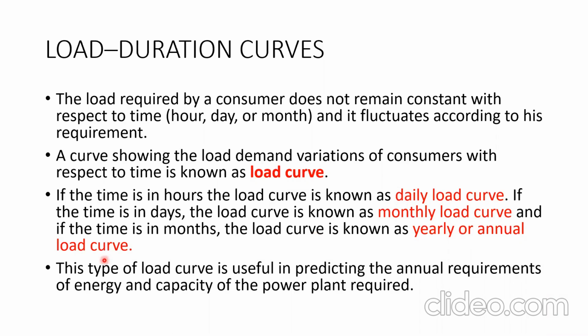The annual load curve is useful in predicting annual requirements of energy and capacity of power plant required. From the annual load curve, what information will we get? We can predict the annual requirements of energy. What will be the requirement of energy in future? We can anticipate it from the current load curve. Also, we can calculate the capacity of power plant required in future to meet the increasing loads.